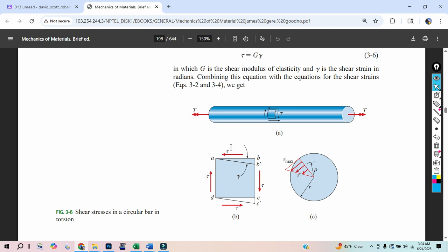So I can draw a free body diagram where I'm putting a force down and a force up. Let's look at that. If I put little rocket engines, one blowing this way, one blowing that way, this thing's just going to spin and get faster and faster. Because this is a statics problem, I have to resist that spin. The only way to do that is put a force here and a force there. And because this thing is square, these are going to be equal and opposite.